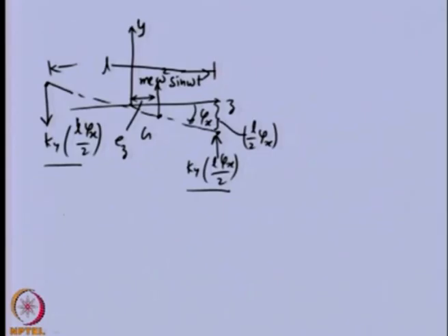From the unbalanced force, this is the force into the moment arm, that will be E z, and that is acting in the counterclockwise direction, opposite to the deformation direction. So, it is negative. Then from the bearing support, you can see this force and this force will give a couple in the counterclockwise direction, that is also opposite to the angular displacement, which is in the clockwise direction. So, this will also be negative.